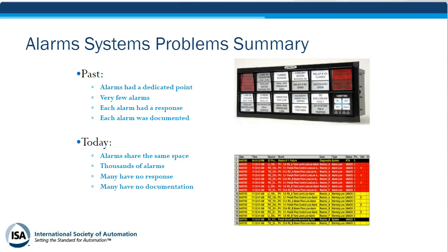I've seen that many times doing alarm management projects. A good example of alarms is when you've got an A and a B pump. The A is running, the B is not, and the B is in alarm because it's not running. You see that in almost any facility where you do an alarm management project. All the equipment that's not running is typically an alarm. That's a good example of alarms that should not be on the screen.